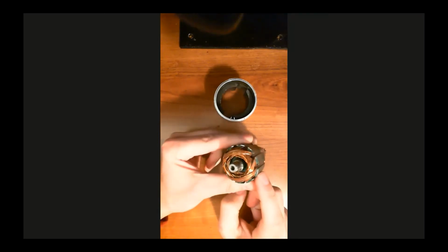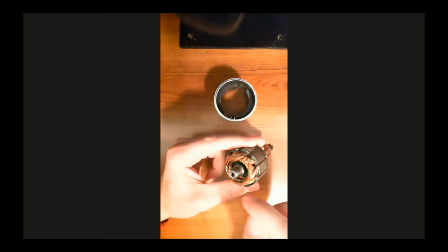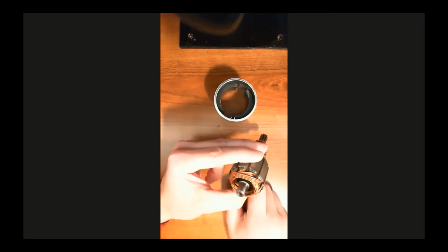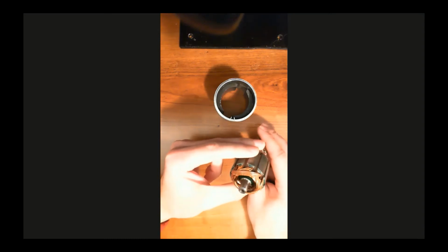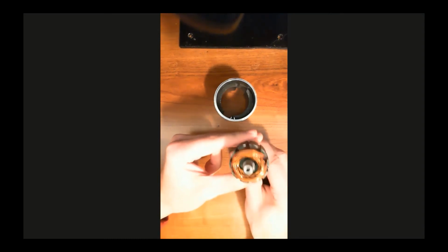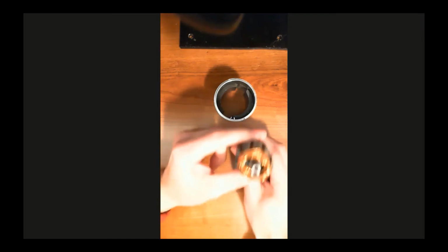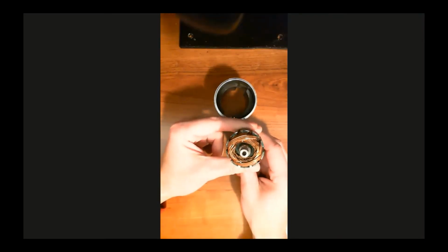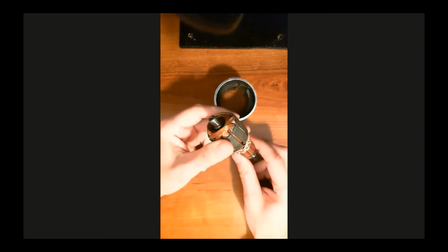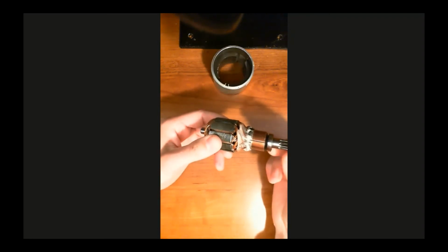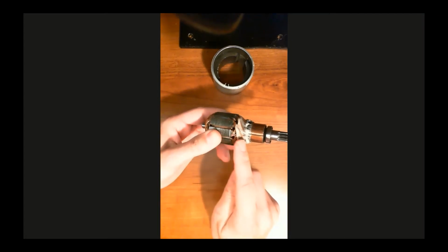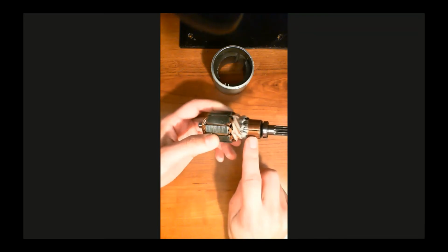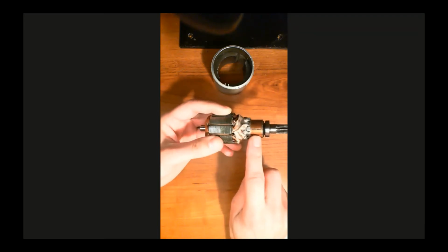Here's the armature. So it's got a bunch of different coils on the armature, all physically rotated a little bit from one another. I haven't counted these. It's probably about a dozen. Sorry, I hope you could see that as I was talking about it. Probably got about a dozen sections of coil on the armature. And then we move this and we can see the wires that are connected from those coils. They're connected to these sections of the split ring commutator. So here are the sections of the split ring commutator.